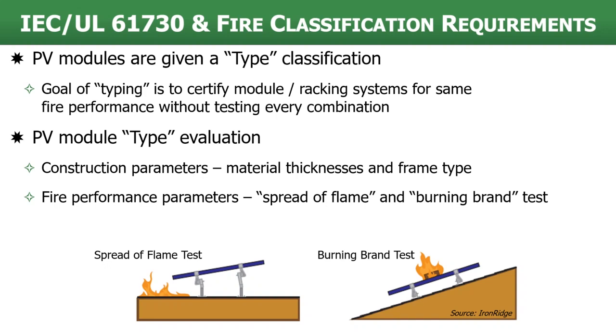And then the other test is the burning brand test, where a burning brand of a certain size is put on the module itself, and it has to be allowed to burn for a certain amount of time before, if it were to burn through, it would catch the roof surface below it on fire. And I believe there are several different burning brand tests. I think they're 1 square inch, 6 square inches, and 12 square inches.